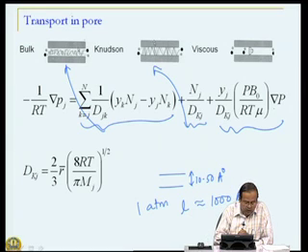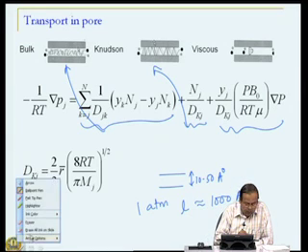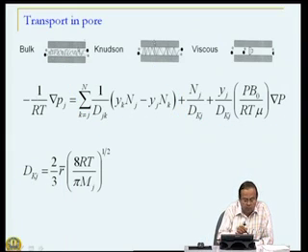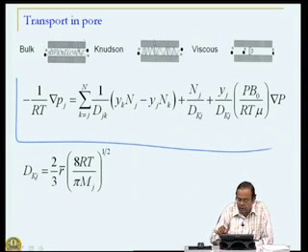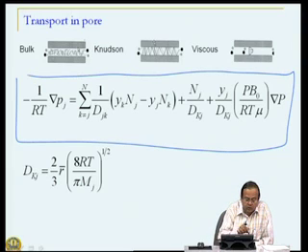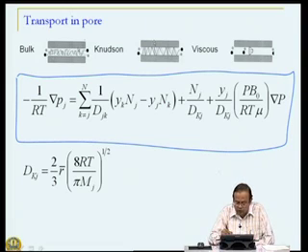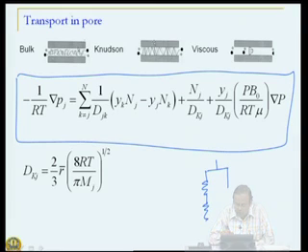What you see here as a model of entire diffusion is what is referred to as the Mason and Evans dusty gas model, which assumed Knudsen and bulk diffusion in series. So, the actual model used is analogy with the electrical circuit.